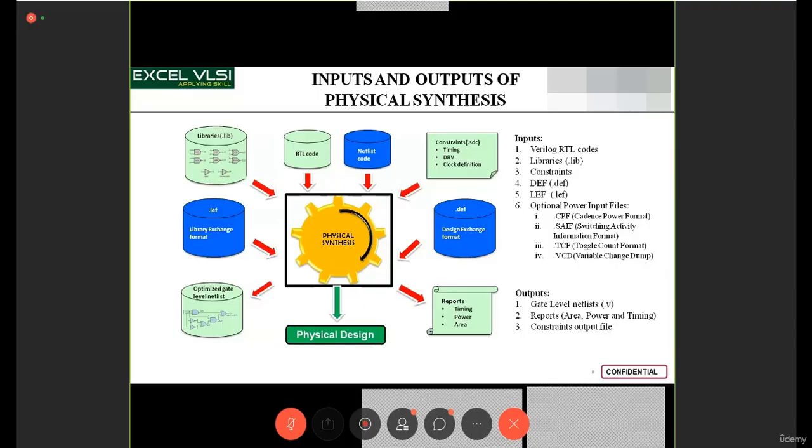What it reports right now is the static power, because it does not have any information about the switching activity. The more accurate power, closer to what the device would realistically consume, will be based on the activity. For example, it is budgeting versus real.